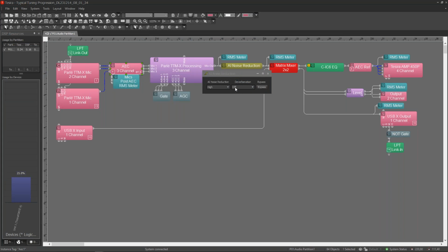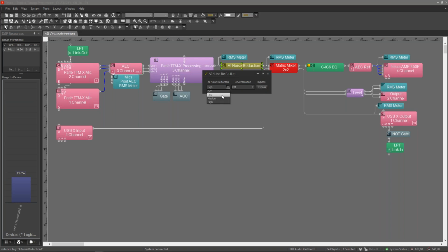And when you're happy with each microphone, bearing in mind there'll be different acoustic paths between microphones, different geometries depending on the mic type and the room, and the levels that they're receiving from talkers, as well as background noise and the effect of reverb. So find a balance for the level of processing that you need to use.